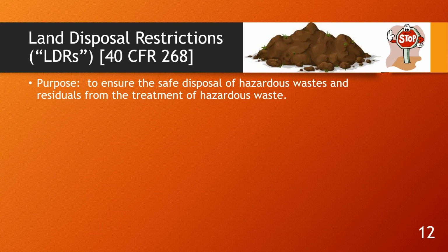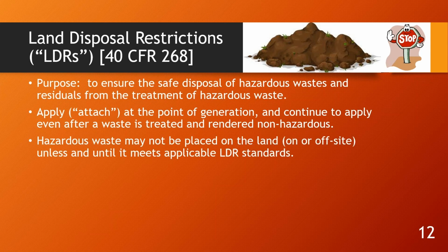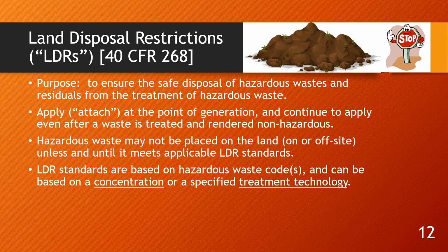I'm going to cover land disposal restrictions very quickly. They can be incredibly complicated. The purpose is to ensure safe disposal of hazardous waste and residuals from the treatment of hazardous waste. At the point of generation, the land disposal restrictions apply and continue to apply until it's either treated and rendered non-hazardous or disposed of as hazardous waste. Hazardous waste may not be placed on land unless it meets the applicable LDR standards. So the importance of this is you're generating a soil that may meet the standard for hazardous waste. You need to containerize it appropriately.